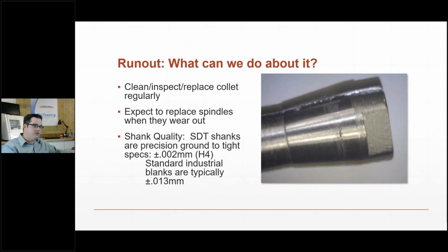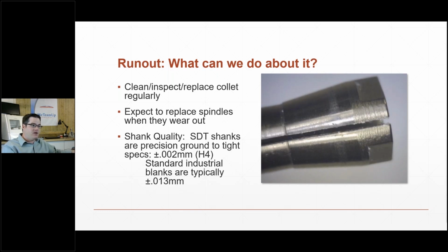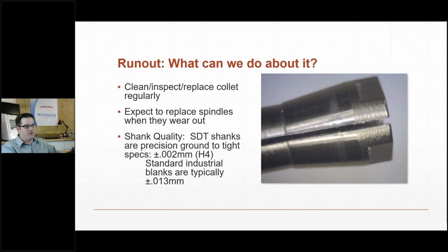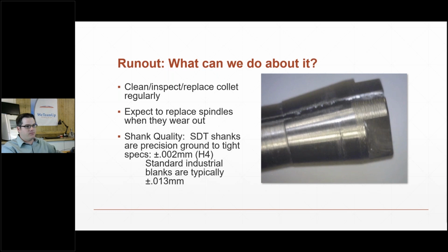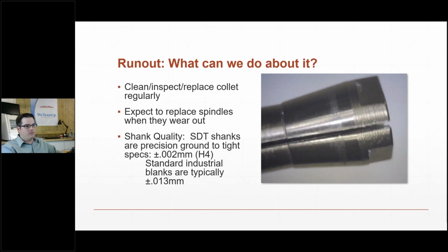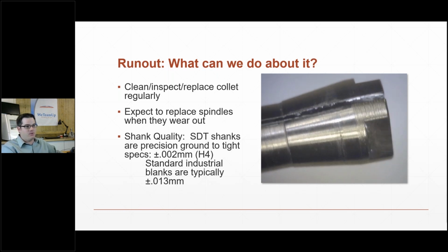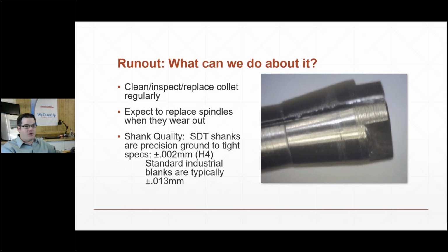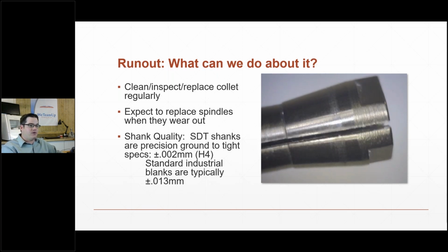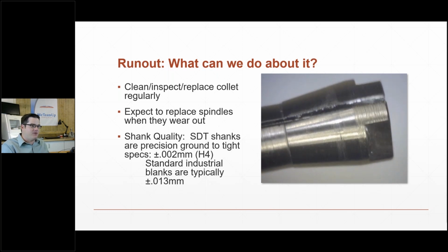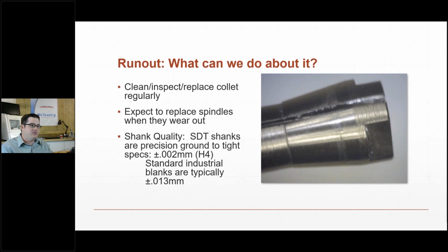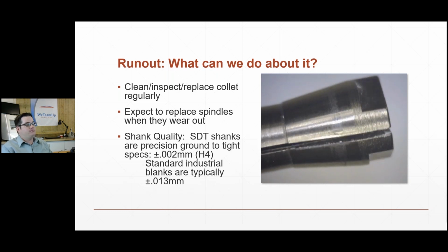So keep them clean, keep them inspected, and if you happen to have an issue where you're suddenly burning up tools, or you've got fit issues or chipping issues that you just can't explain, the first thing to look at is the collet. I'm always fairly surprised when I run into labs that don't maintain the collet.